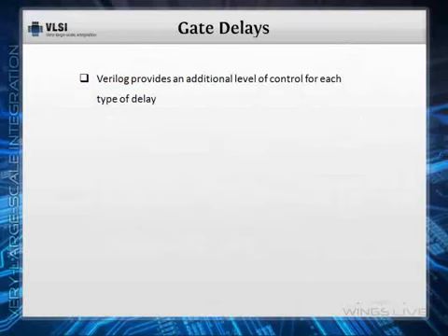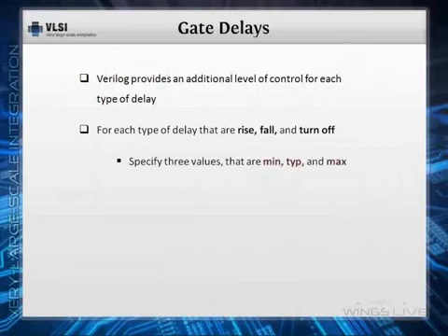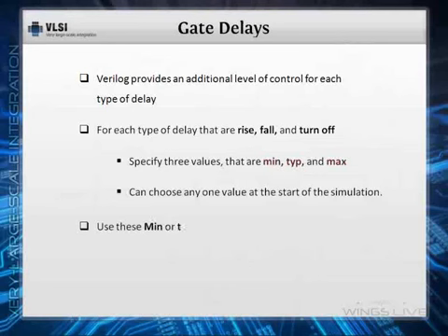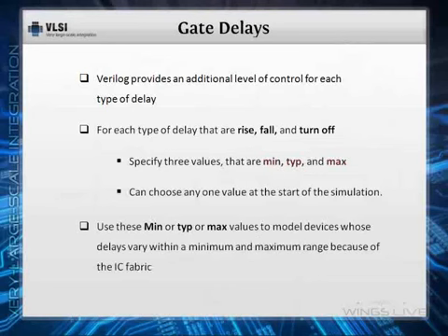Verilog provides an additional level of control for each type of delay mentioned earlier. For each type of delay, that are rise, fall, and turn-off, we can specify three values that are min, typ, and max. We can choose any one value at the start of the simulation. We can use these min or typ or max values to model devices whose delays vary within a minimum and maximum range because of the IC fabrication process variations.